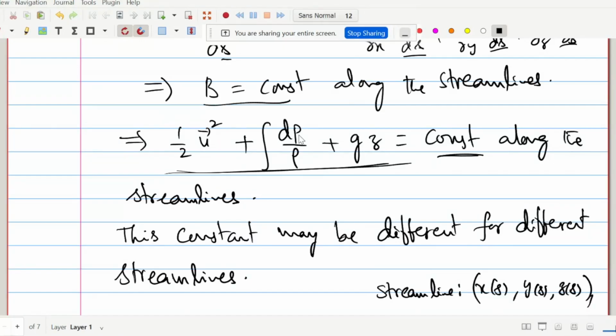Now you consider irrotational and incompressible flow, del dot U equal to 0. You already have grad phi, so del dot grad phi is nothing but the Laplace equation. So you have a Laplace equation throughout your fluid. You have a Laplace equation, that is 1 PDE.